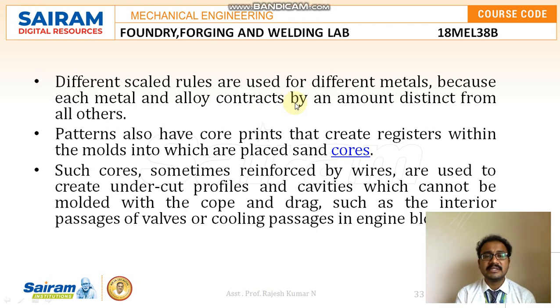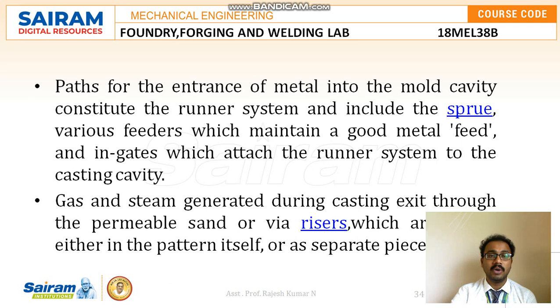And different scale rules are used for different metals because each metal and alloy contracts by an amount distinct from all others. Patterns also have core prints that create registers within the molds into which are placed sand cores. Such cores, sometimes reinforced by wires, are used to create undercut profiles and cavities which cannot be molded with a cope and drag, such as the interior passages of walls or cooling passages in engine blocks.